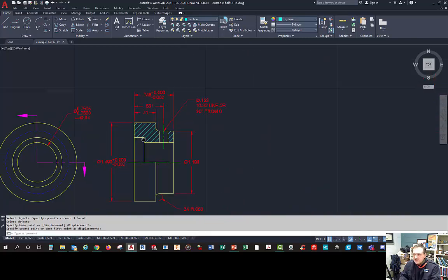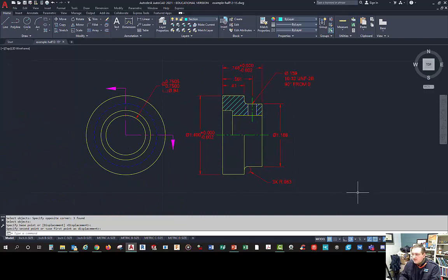Now, one of the reasons that those are showing up is I have the magic triangles on down here. This one you want to have on because it shows annotative objects, and everything we're using is annotative. Text, multi-leader style, dimensioning, okay? Beat that into your brain, please. And then here is your other magic triangle that says show, oh no, I'm sorry, I'm reversed. This is show the objects, so that one has to be on. This one shows scale changes.